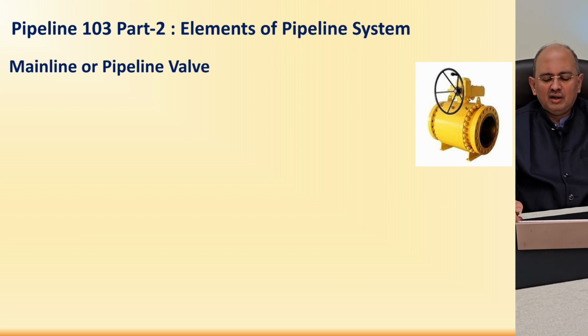So we want a through-and-through opening in the pipeline across the valve, and therefore all the elements in the main flow path or pigging path should have proper ID control. The ID should match the pipeline pipe ID, so that the pig can travel through and we can maneuver the pig across all such elements. So it is one of the critical aspects of designing the pipeline elements.